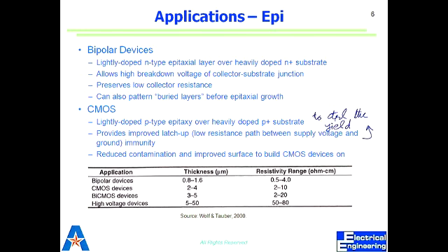How can epi create a buried layer? When you do an epitaxial growth on top, what is below it is buried down. But that's only a part in the transistor, right? The rest of it is not heavily doped. It's only one small part of it, and that part will now be buried under that lightly doped material. So you grow the lightly doped on top of that.